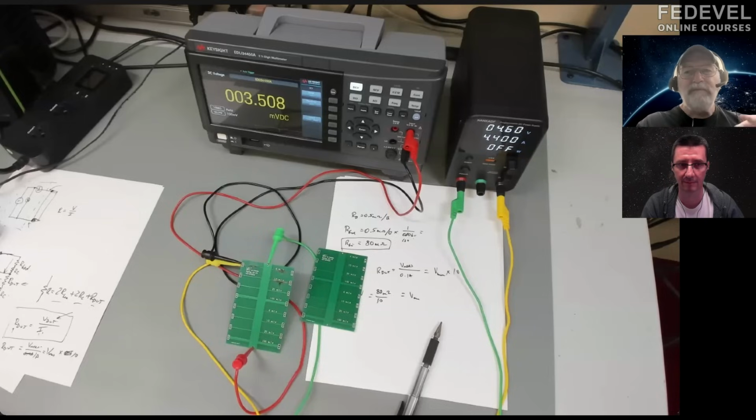You've got this nice wide plane, it's low resistance, you can carry a lot of current in it, but you have to get that current up to the package, the device, through the vias. And you've got limited series resistance and current limitations in the vias. And that's what you design for. So you have power planes and then the vias. And that's for a low-end processor.